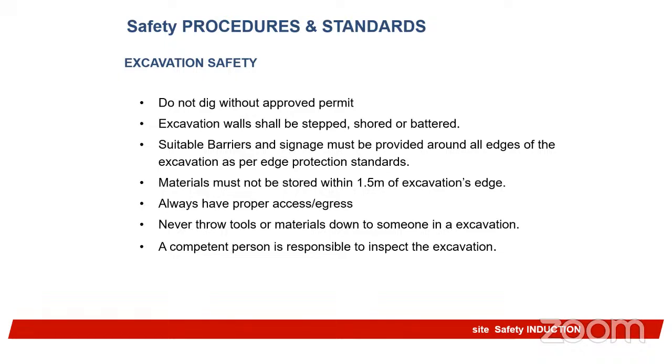When someone is working at the edge and something is dropping directly, the person does not see it, based on the impact of work activities around the edges too. Even walking around the edges of excavated areas is also very dangerous, because even the soil can become weak and fall on those walking underneath.